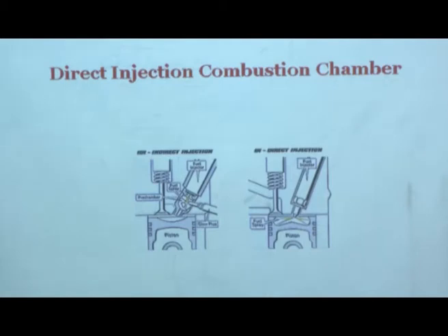So to overcome this, you have a finger heater. It's a ceramic based finger heater which is called glow plug. Before you start the engine, you allow the flow of electricity into it. So this becomes red hot, and once it becomes red hot, it will do radiative heat exchange with the walls of the pre-chamber and make them a little warm.